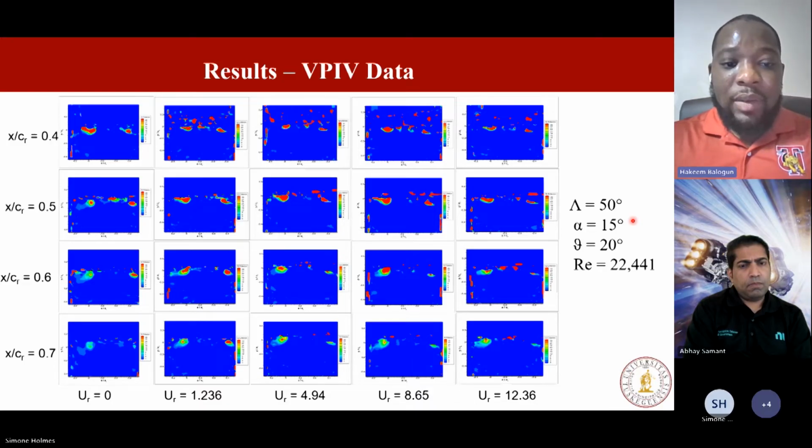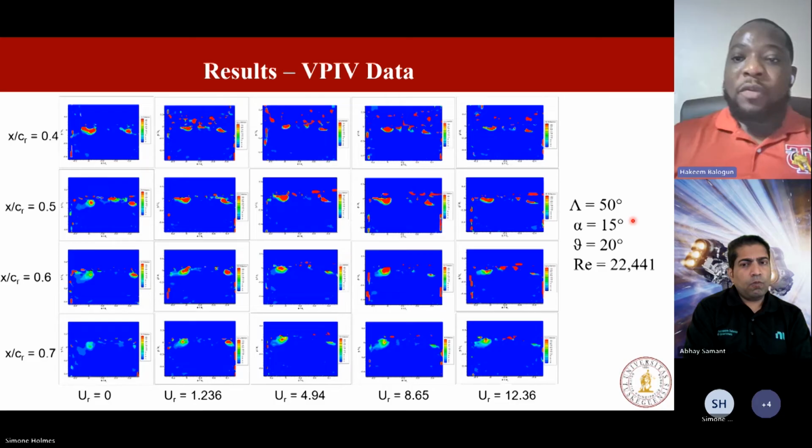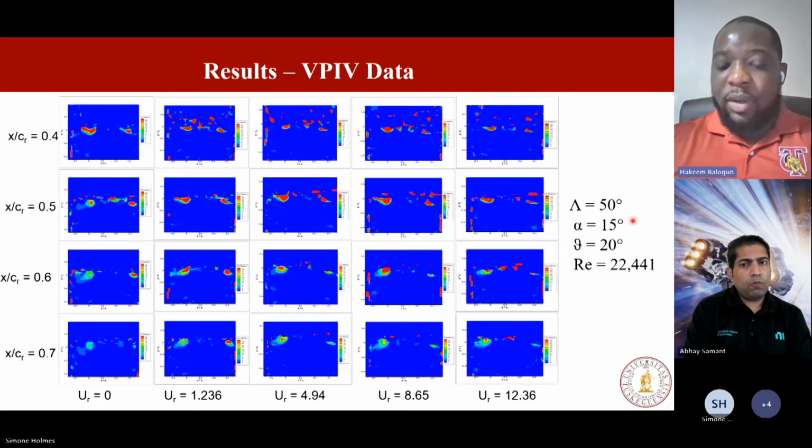wing. And after the breakdown area, the diffused vortical structures continue to swirl along their respective axes. And this movement is pronounced and was readily visualized with the dye flow data. So looking at the PIV data, on the far left, I have the root chord vortex breakdown stations, and they go from 0.4 to 0.7. So from 40% of the chord to 70% of the chord.